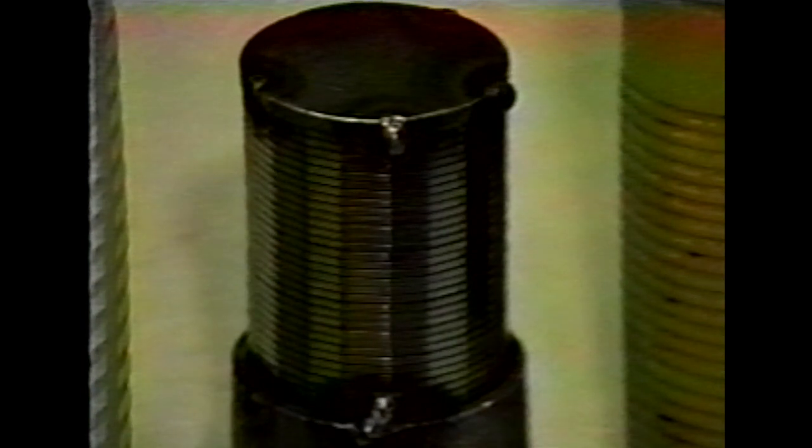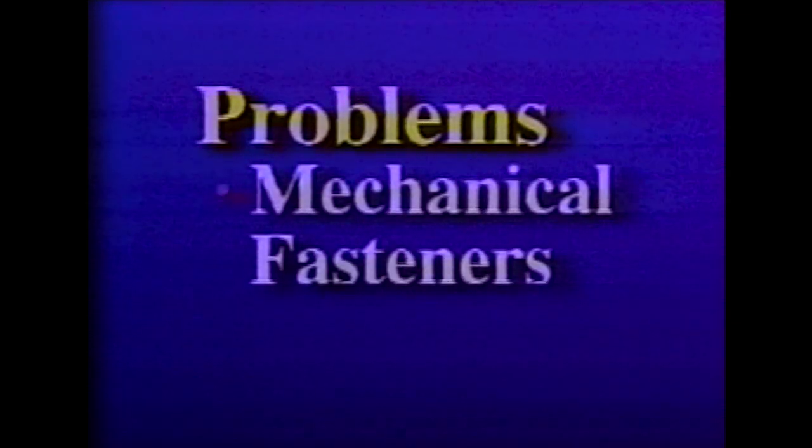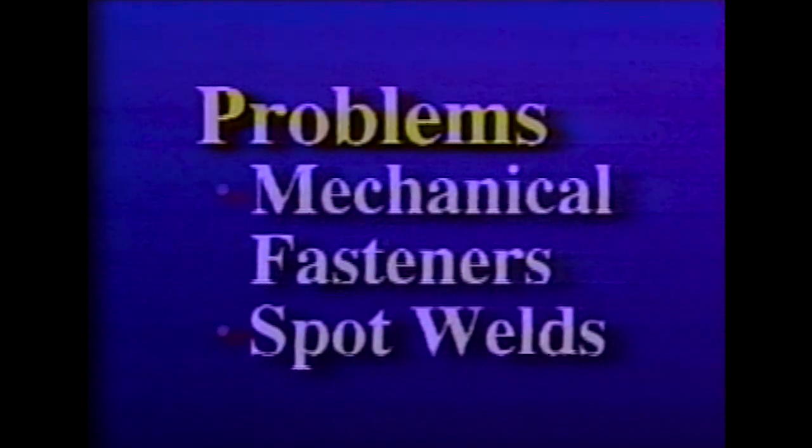One should note that some manufacturers use mechanical fasteners or spot weld the slots to the underdrain pipes. There can be problems with either the mechanical fasteners or the spot welds. The mechanical fasteners may vibrate loose or come loose during shipping. This can be easily checked by the installer. One should also check the quality of a weld.